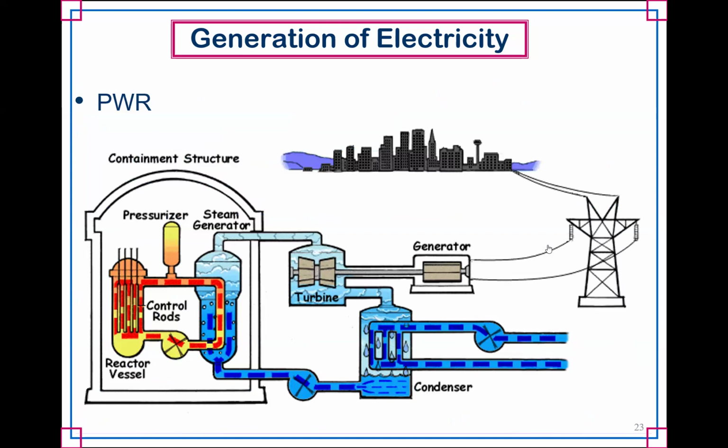So here's a pressurized water reactor. We can see that we have our reactor with our control rods. Our pressurizer maintains the pressure of the reactor at a certain point. Our reactor coolant pumps are what circulate the water in through the steam generator. You have clean water, but not radioactive water, that heads out to the turbine, which is mechanically coupled to the generator. And then the generator feeds transmission lines. So you're stepped up in voltage, and then that goes and distributes the load.